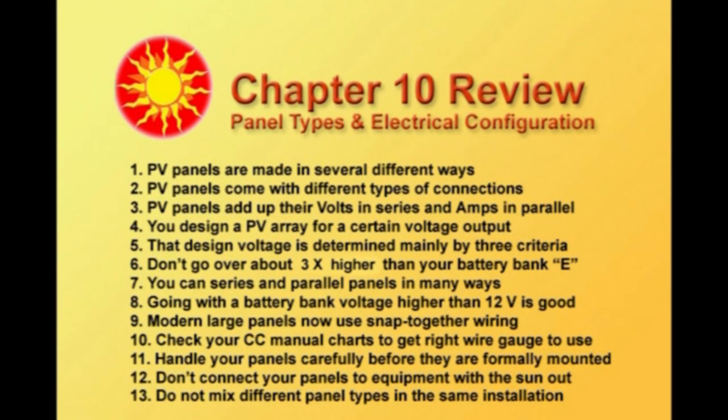Check your charge controller manual because it has charts that tell you the right gauge wire to use coming in from your panels. Handle your panels carefully before they are formally mounted because they're not that strong. And don't connect your panels to any of the other equipment with the sun out. You can connect between the panels, but that final connection to the charge controller, don't do that with the sun on the panels. And last, do not mix different panel types in the same installation.